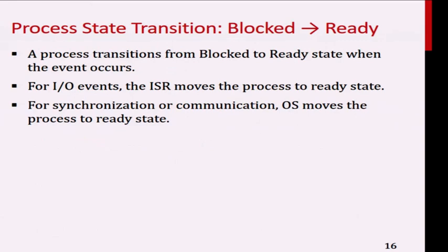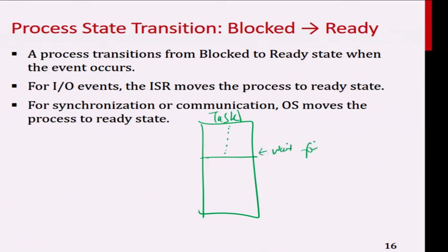Okay, so this is also another important thing you must understand. Let's say I'm in task 1. I run, and over here, I decide to wait for a resource, for example. So all the while here, I am running. Before that, you were in the ready state first, and then you run. At some point of time, you are waiting for a resource. So when you're waiting for a resource, you get blocked.